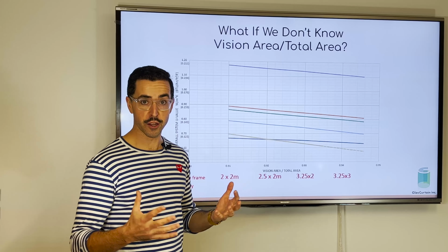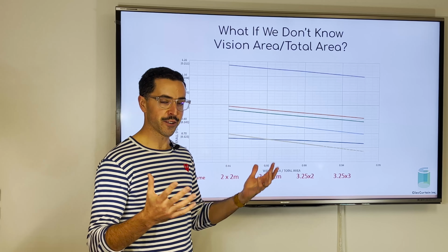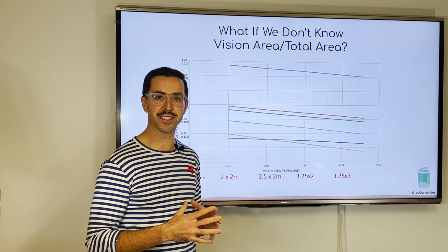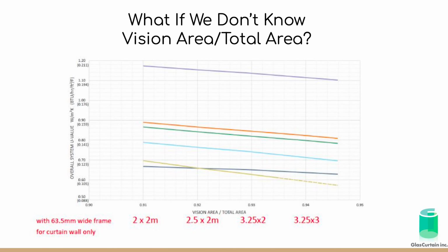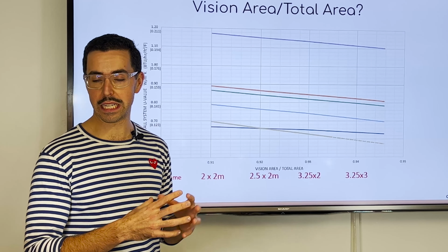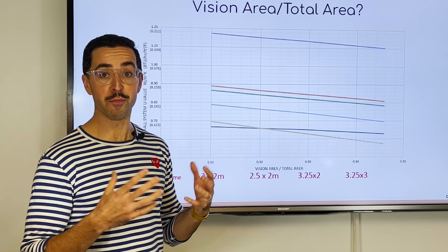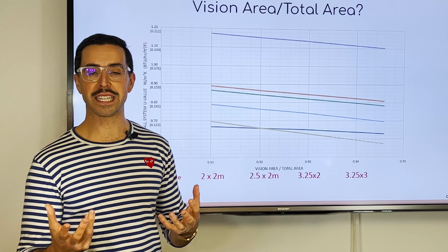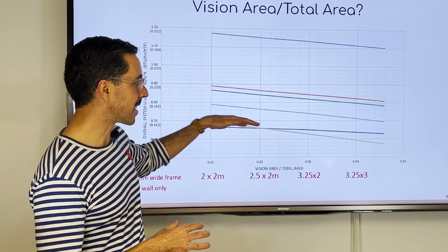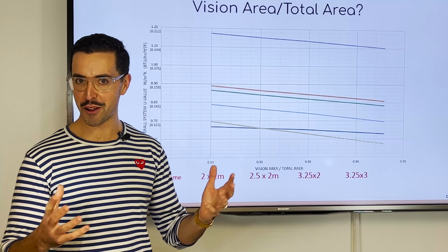So what we're seeing is that the thermal performance just gets better and better. The larger the piece of glass, yes, the heavier it is, and there are definitely cost implications of that as well. But we do see that the thermal performance of the overall system improves. But we're actually penalized a lot less in a fiberglass system relative to aluminum frame systems for using smaller glazings. So for certain design aesthetics that use smaller glazings, there's much less penalty for using a fiberglass framing system compared to an aluminum frame system. So these lines in general are very flat, and we can accommodate all different sizes.